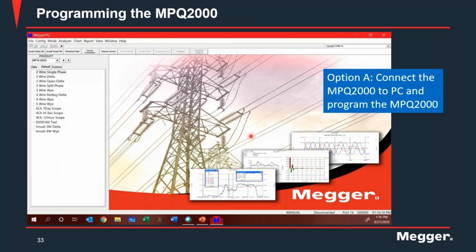Programming the recorder. There are two ways in which you can program the recorder, either directly by actually connecting the recorder to your laptop. So you follow the steps that we covered in the previous slide. You connect your recorder to the laptop, and then to program the recorder, you will either go with analyzer and load setup, or click on install setup file, which is the main option that's provided. Both of them are basically the same thing.